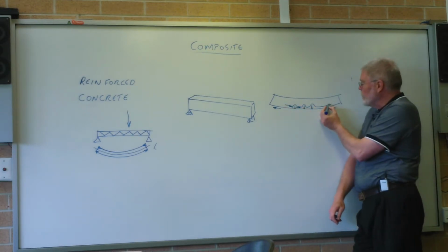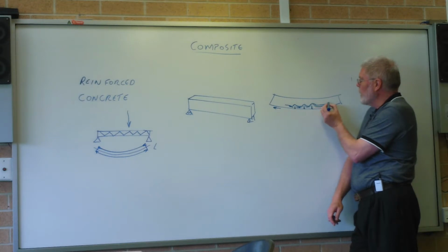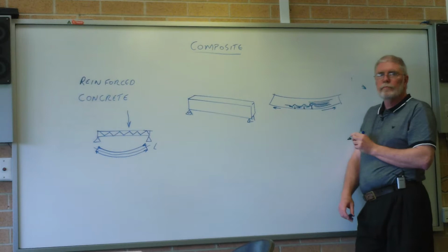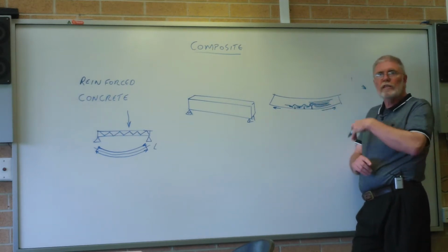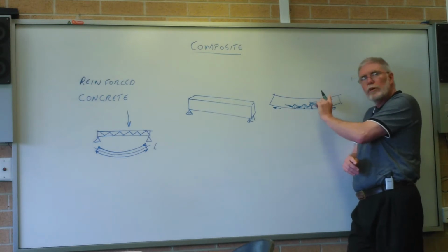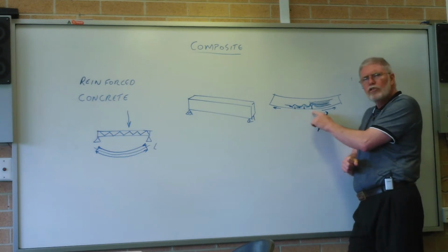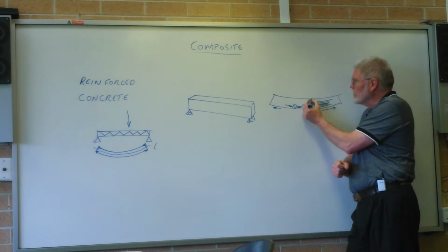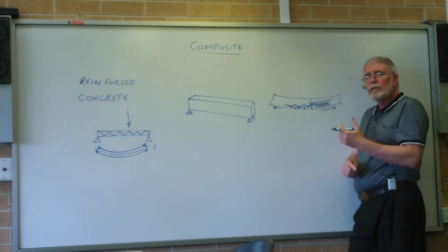And the loading in the material above that goes up and over the crack. And the one above that goes up and over the crack, and it bunches up at this point above the crack. It's actually known as a stress raiser. It raises the stress, or concentrates the stress, at the tip of the crack. Does that make sense? It should, because you can't go through the gap. So the material is actually thinner at those crack points, and that causes a whole bunch of other issues for us.